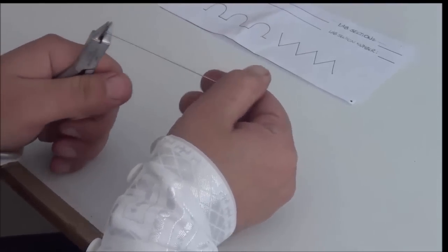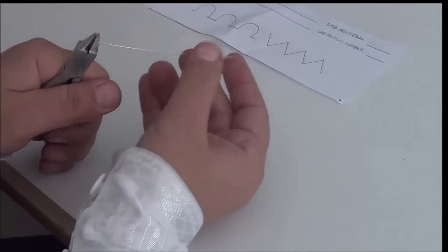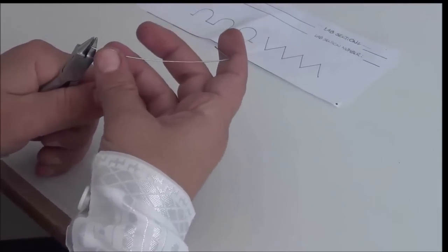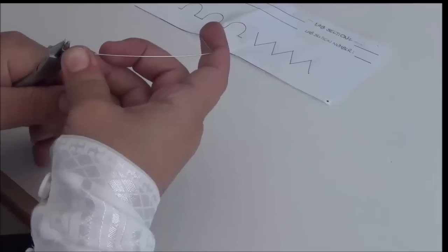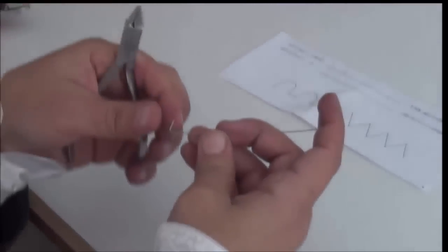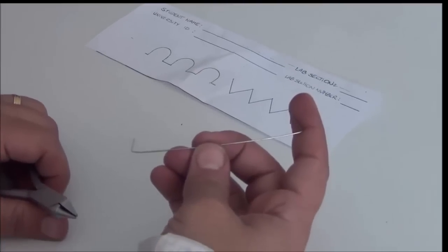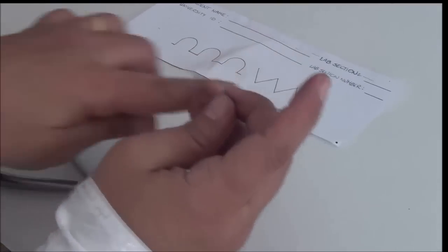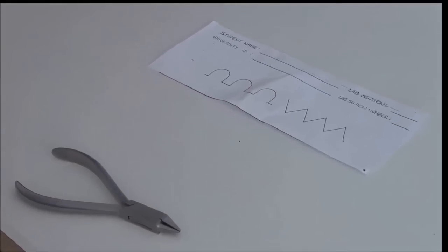Once I have a good grip and it's stable, not moving around, I could further bend it. I'm fixing from far away, and I further bend this. I increase the bend. So what do I get? I get less than 90 degrees. So this is the way. This is how we do angles. Now, how do we do curves? These are a bit more tricky.